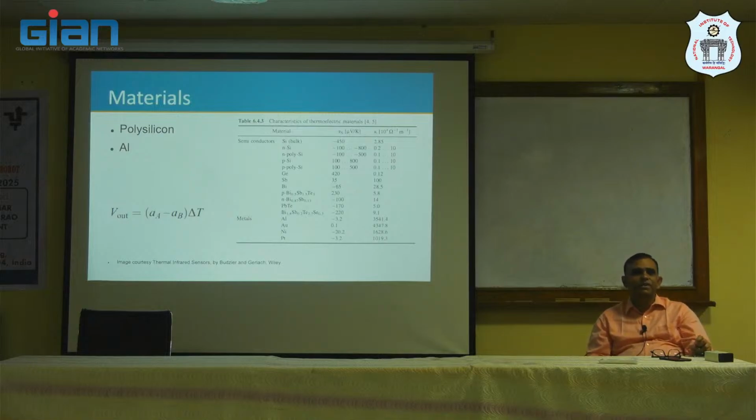But yesterday when we were doing layout, those who were doing layout saw we had metals, metal 1, metal 2, metal 3. In most larger processes, we used to use aluminum as a metal to connect transistors. This is very interesting because I already have polysilicon and I have aluminum, which means I can make such sensors on a classic silicon chip without introducing any other material. The whole crux of my course is what can we do on a silicon chip. You can have fancy materials and we can add loads of these things.